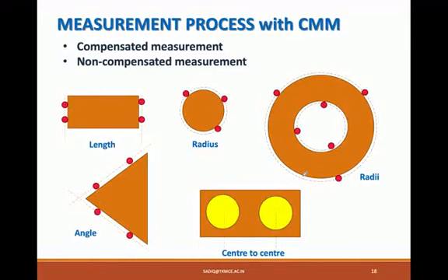I would like to tell you about another concept in CMM measurement, called compensated measurement and non-compensated measurement. I'll give you examples of compensated measurement. If we want to measure the length of this cuboid, I have told you that we have to define a plane like this by picking points here, and picking points here, we are defining the plane.